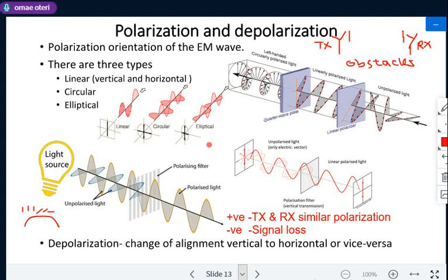Please know that you are going to do design. The antenna designs should incorporate such. In fact, you can have what we call diversity in space. We usually call it space diversity. And as a result, the antenna can actually be able to receive a signal which is maybe horizontally polarized and also vertically polarized.